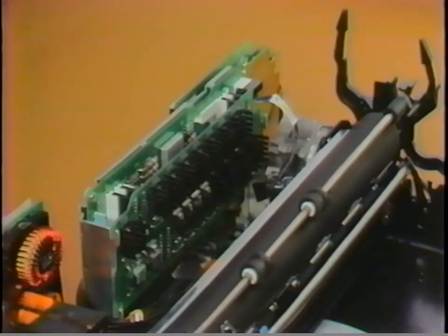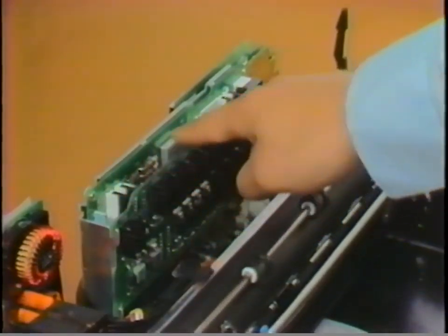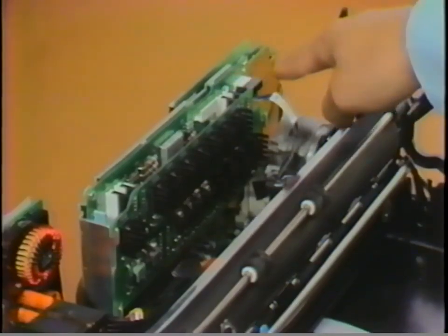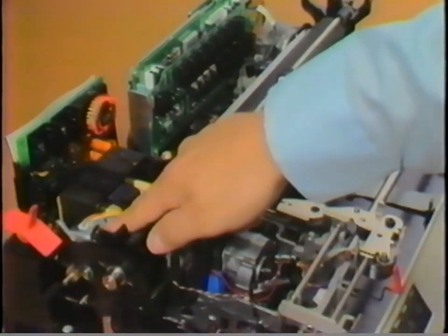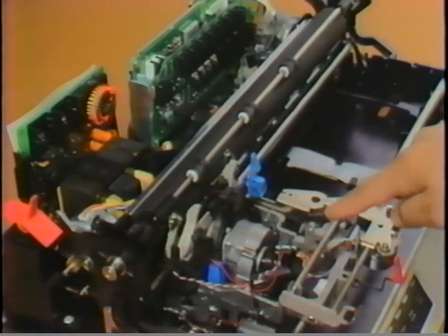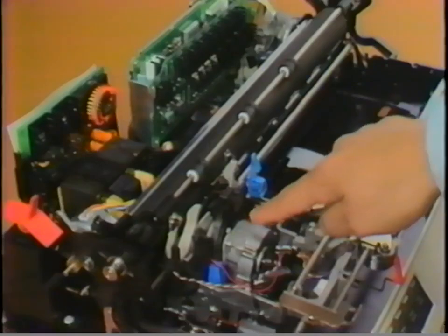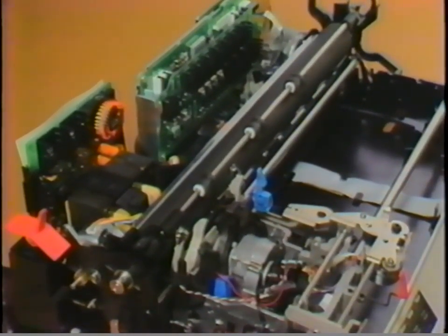The function board processes input signals from the host system, the control panel, and the SAPI switch, and sends output to the printer board. The printer board, which contains the motor drivers, receives the output from the function board and sends signals to the transport motor, the paper feed motor, the ribbon motor, and the selection motor to perform the printer operations. It then informs the function board when the operation is complete.